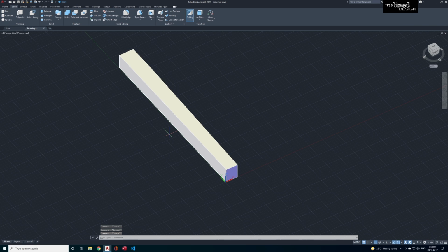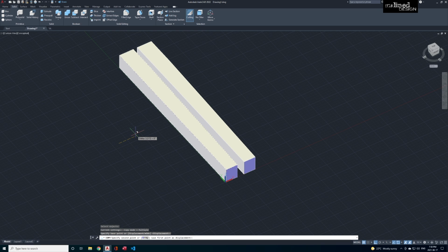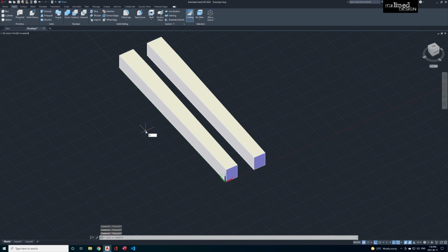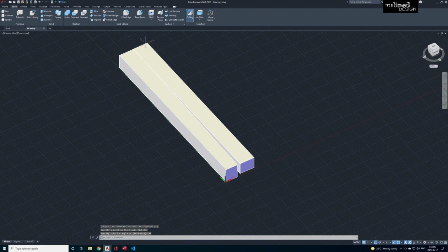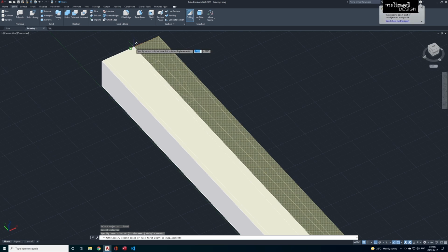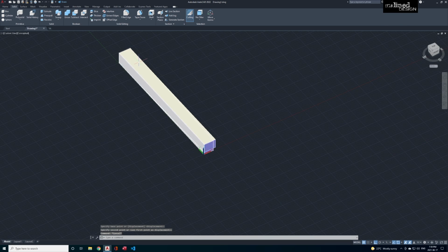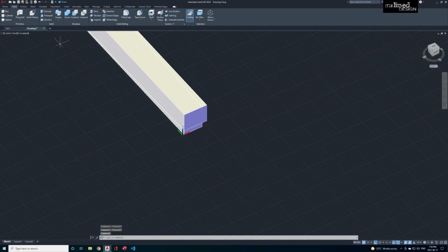But if you already have a drawing and you're extruding it, and it's got a different type of pattern to it or something, you just copy it, move it over by 5, rotate 3D, and select the object, enter, Y, enter. You just pick this outside corner here, 90, and then basically just put the two objects together, outside corner, and you can see the two legs overlapping.